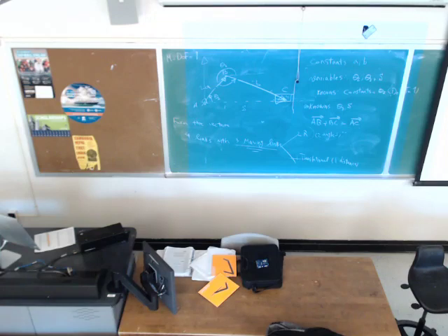The magnitude of this is the length of this times the angle of this vector from the ground. The angle is theta. The length of the vector is A. A cosine of theta is going to give me this distance. Y component of OA is this length, or this one, which is A sine of theta. Good? These simple things are going to help us derive the equation of displacement from that vector loop equation. Everybody can see this. All right.